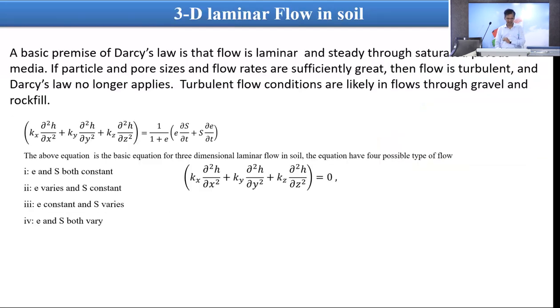Okay, this equation, the flow through porous media, is important in terms of both permeability and consolidation. I say this is only one equation. If you see, this is the flow through porous media equation. So I have got two parameters: one is the void ratio, the other is the degree of saturation.